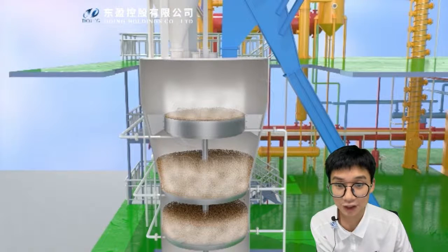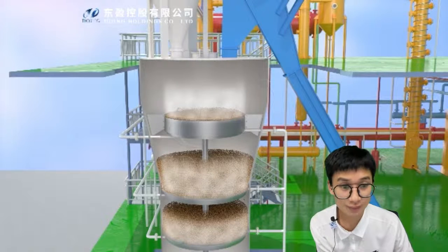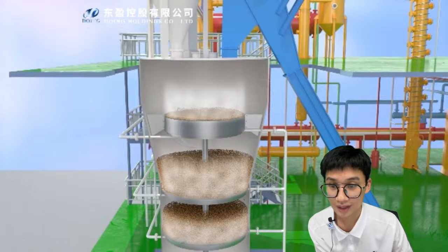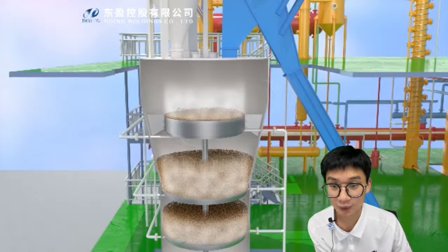The pre-desolventizing function is to use the mixed steam and the interlayer indirect steam of the lower layer to preheat the wet meal and remove a small amount of the solvent, so as to prevent excessive water vapor condensation in the meal when the direct steam or mixed steam of high temperature in the following layers contacts the low temperature wet meal, resulting in wet meal agglomeration.